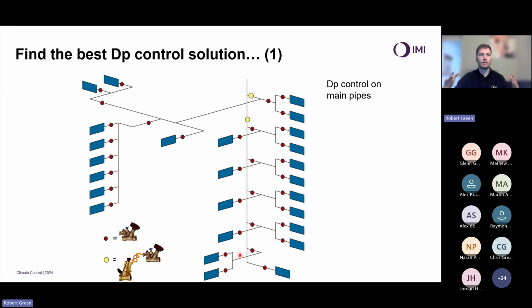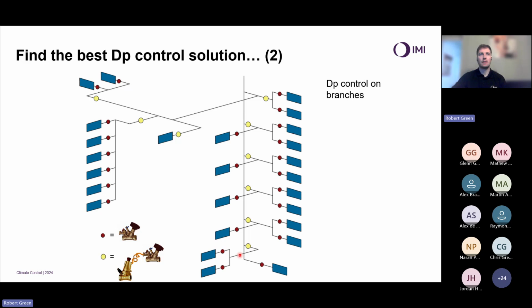Now that's pretty wide arching. We are providing a stabilized differential pressure across quite a large area. So that may not be enough, depending on, and we'll talk about things like valve authority, control characteristic in 2 sessions time, but there may be other options. Other options, we could look at, again, standard DPCVs on the sub-branches. So now each sub-branch is containing a differential pressure control valve.